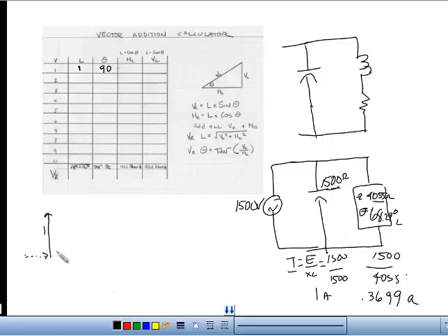Negative angles, positive 90 capacitive, negative 90 purely inductive, but this is only 68.29 degrees inductive, so it's not coming horizontal, it's coming down about 68 degrees, and it's only going about 0.3, and I'm not really at a good scale there. So what we're going to come up with is our final vector.